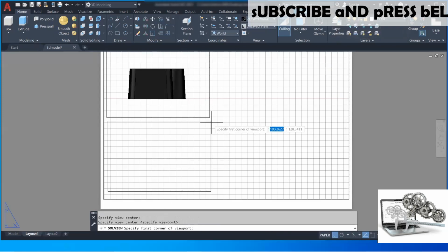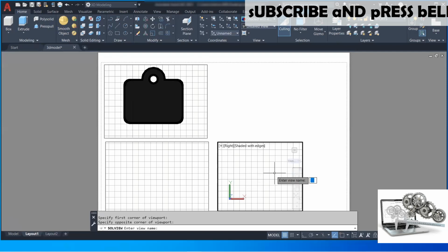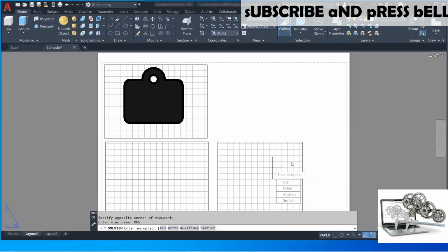Now it is asking for the view center, press enter. Now first corner, click somewhere on the position shown in the video, then click on the other corner. Now it is asking for the view name, so give it as RHS, that is right hand side view.